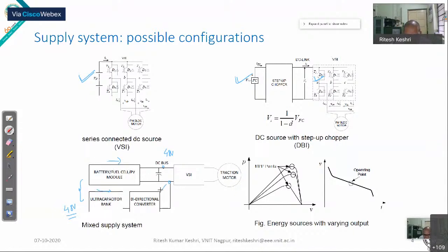Okay. What will happen if this is not there? You are going to accelerate. Normally you know that if the nominal current requirement is 20 ampere, when you accelerate, you will be drawing 40 ampere of current. So under such a situation, what will happen here? If this is not there, you remember the IV characteristic of a battery. Depending upon your speed, at what rate you are trying to draw the current, the voltage drop takes place here.